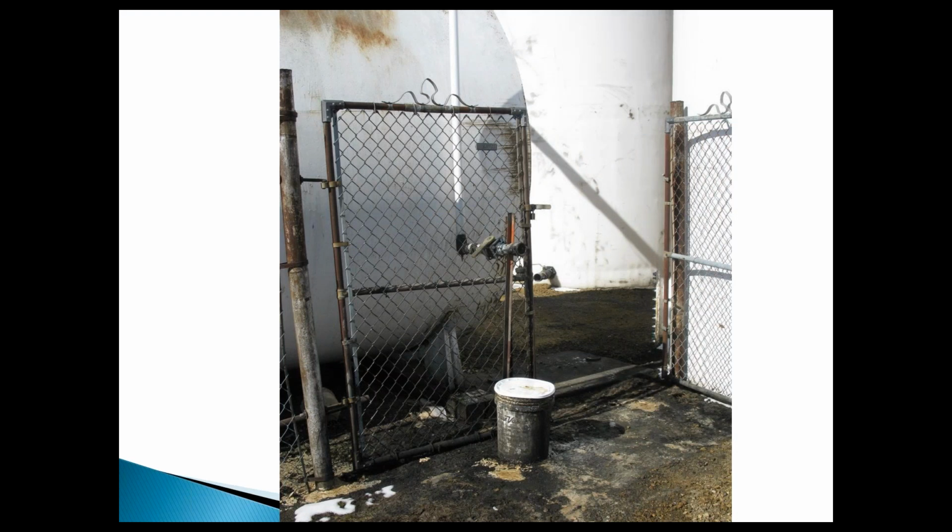Buckets of oil, housekeeping typically means there are problems. If you look at this facility, they have gravel all over the bottom area of the tank, so it can't be inspected. They have ball valves. If you look at that tank in the middle, a ball valve that's unsecured could release the entire contents of the tank, along with this other one. It looks like a stinger that goes to the top, but the one in the middle, you literally could walk by, accidentally hit that ball valve, start a tank leak and not know it, and drain the entire contents of the tank.